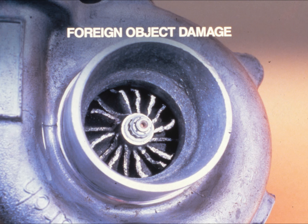Foreign object damage will cause an imbalance of the turbocharger rotating parts. Any nuts, bolts, or similar debris left in the intake system will damage the turbocharger compressor wheel. If the intake system is defective, dirt entering the system can damage the turbo. A valve failure, or a similar internal engine failure, can cause foreign object damage to the turbine wheel.